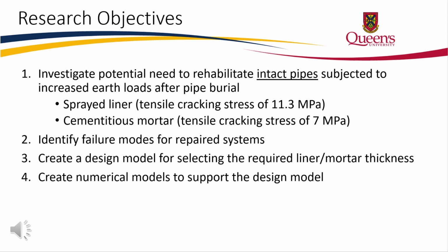Identifying failure modes for cracking brings us to the third objective, which was to create a design model that can be used to select the liner mortar thickness required to restore the pipe to a sufficient bending moment capacity to prevent cracking. Finally, the results of the design models were evaluated with numerical models.